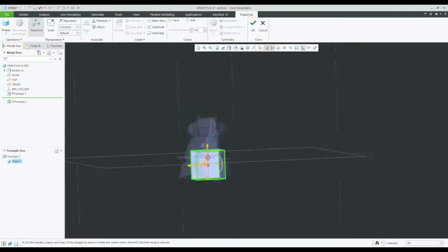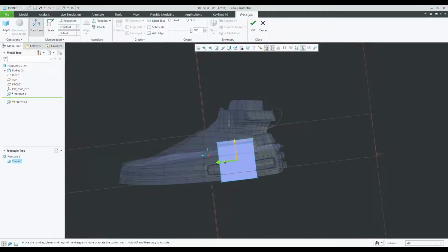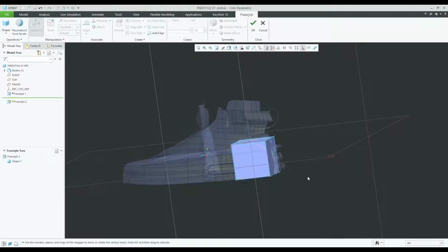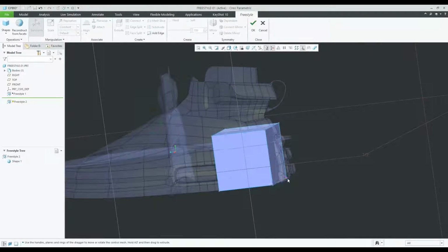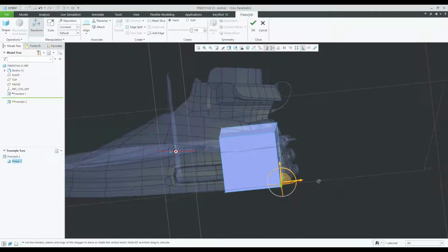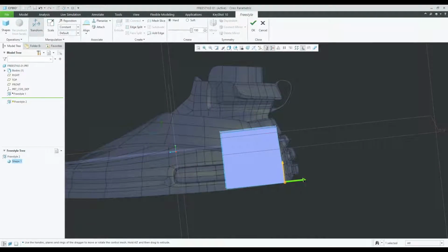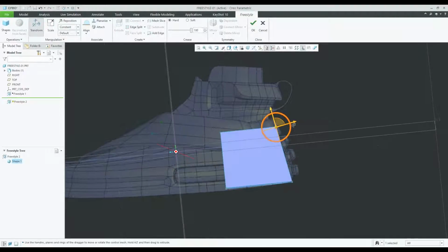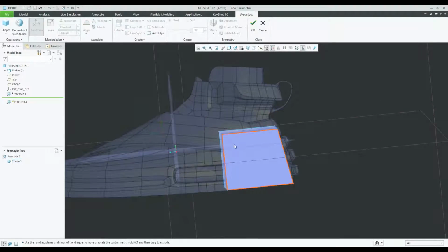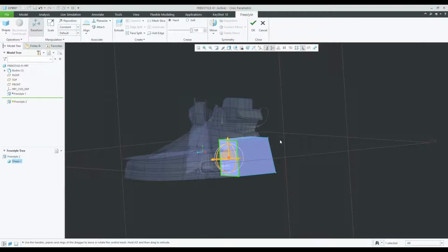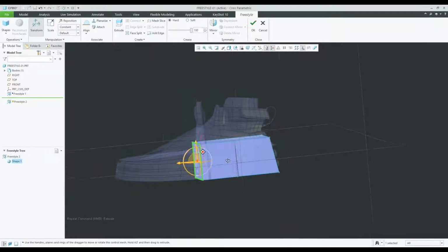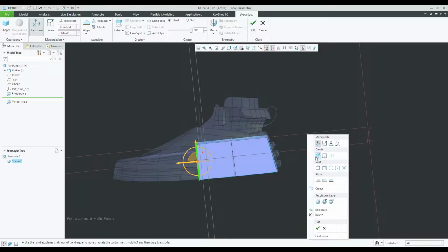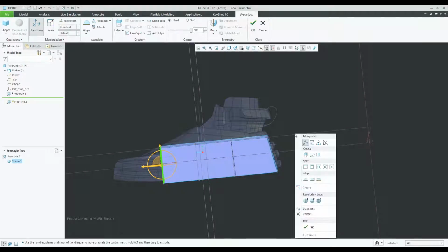So we got one there, and I'm going to go in this view and then drag this to my starting point, about there. We can extrude the face. I can grab a face and extrude. I can grab an edge or a datum point or a vertex, sorry, and move that. So basically what you want to do from here is start sculpting this out. Then I'll take this surface, right-click and extrude that, and extrude again, and extrude once more.